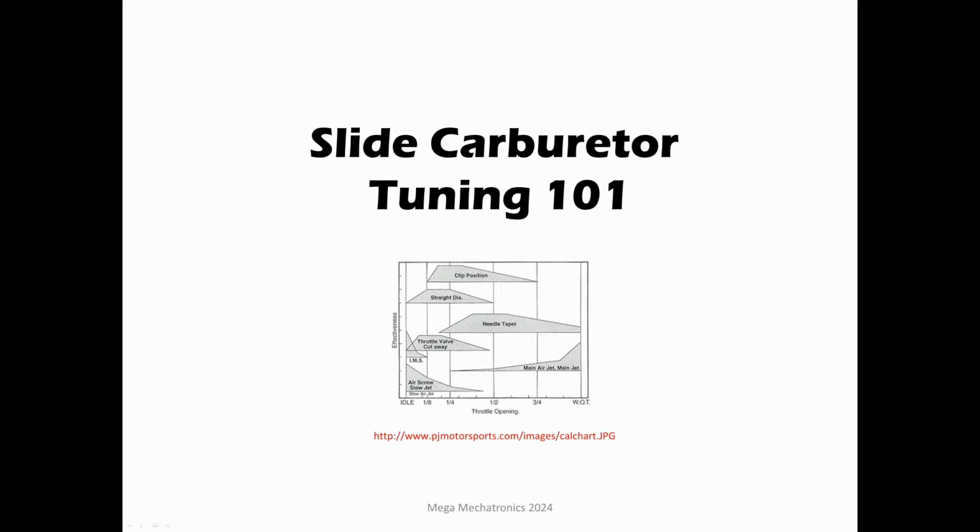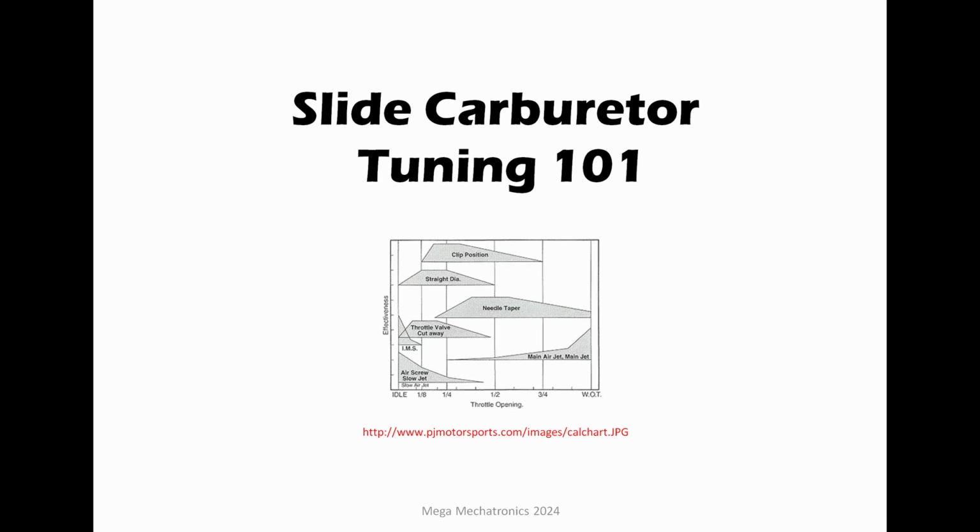And better yet, have that EGT as a secondary, more robust system, where there's less of a myth saying that your EGT is going to just stop working after 5 minutes. So you can run that EGT all the time and get a really good idea after you've run that wideband and set things up. So you're wide open throttle, sustained, you're climbing, on a hill climb or climbing up in a paramotor, and you get a certain temperature and you're 12-to-1. Let's say 12.5-to-1 is your target, and you have a certain temperature. That temperature is now gold. You can write that in stone, all things the same. You didn't make modifications to the engine or change the fuel. You would want to re-verify that. So next time you're climbing full throttle, you can look at your EGT and see how you're doing there.